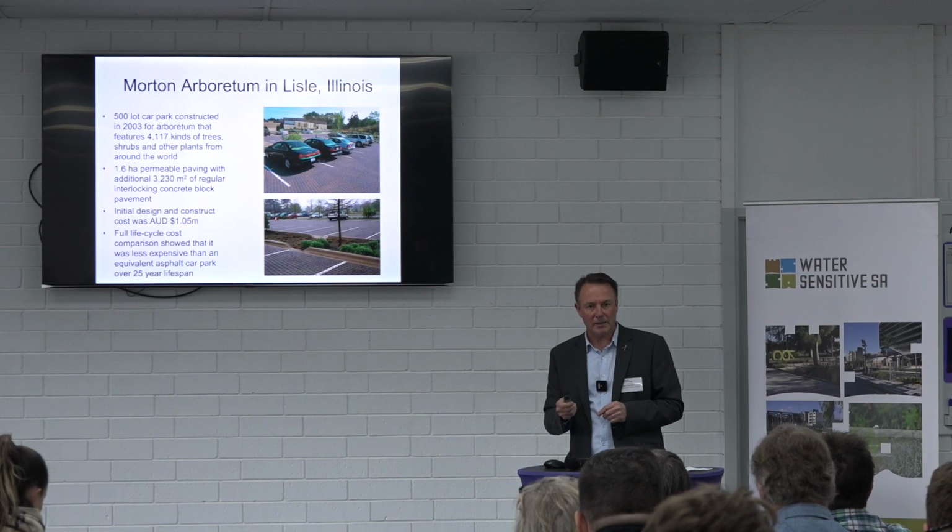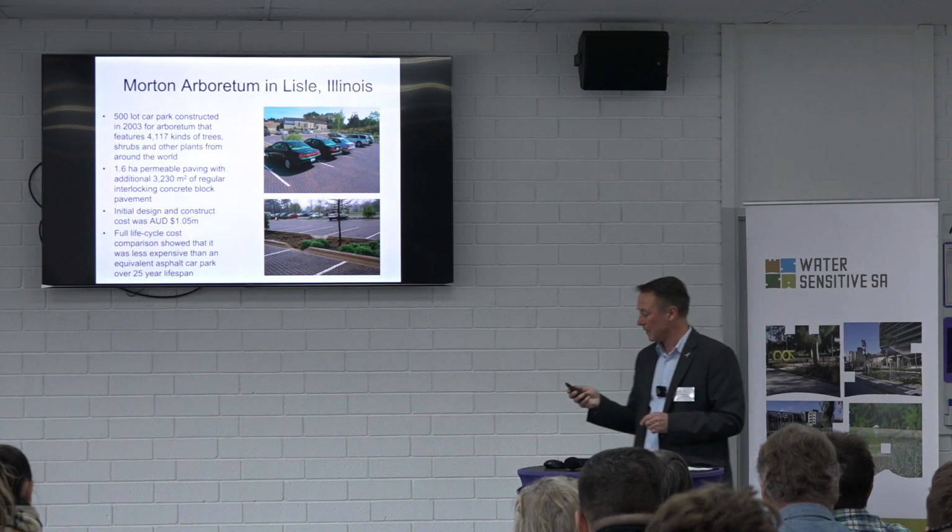And that's because designers only include, when they spec up, their construction costs and the design and construction costs. They don't spec up whole of life costs. When you do a whole of life cost for any system, it's cheaper to put in paving systems. Okay, 2006, Interlocking Concrete Paving Association UK 2006, it's freely available on the web, 250 projects redesigned. Have a look at it.